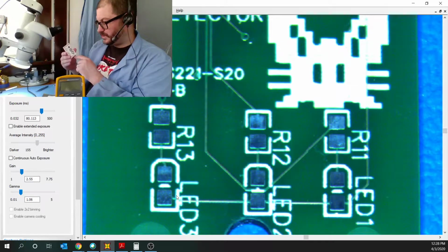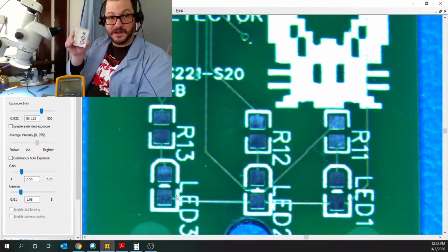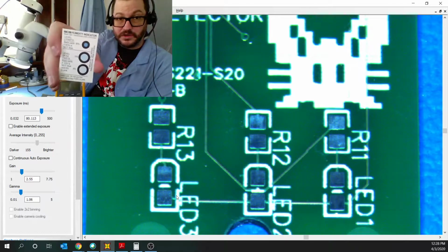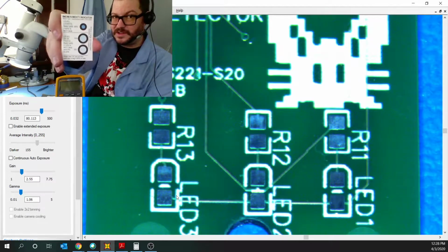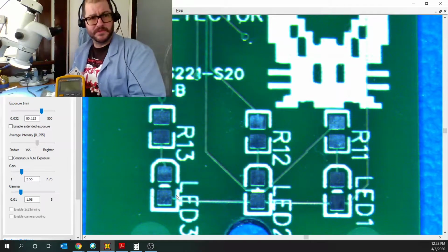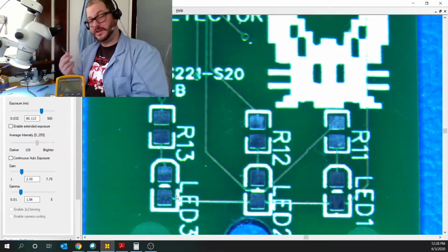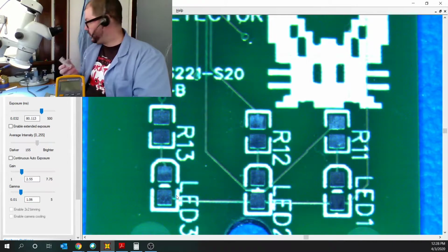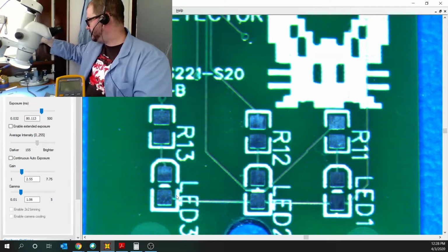Initial use, do not put this card into the bag. If the 60% spot is pink, if the top one is pink, then we wouldn't want to do this. So this is kind of a measurement tool that measures how much moisture is on the inside of this bag, so to speak. It tells me the moisture level is here. I'll leave this outside to watch it change colors.